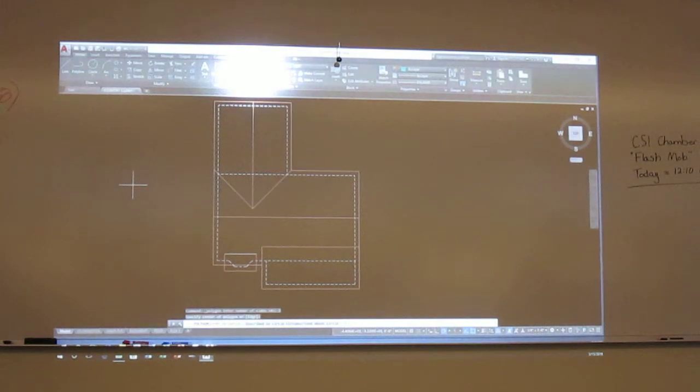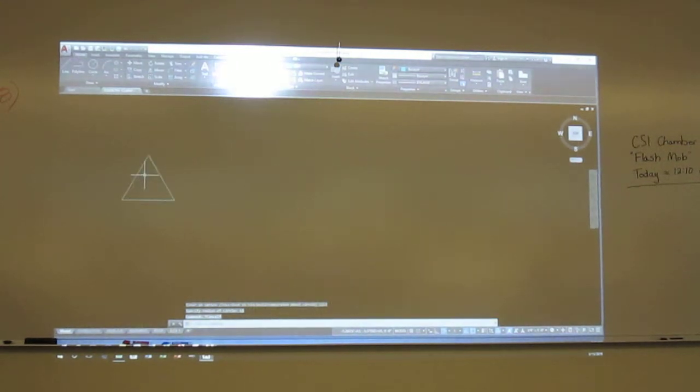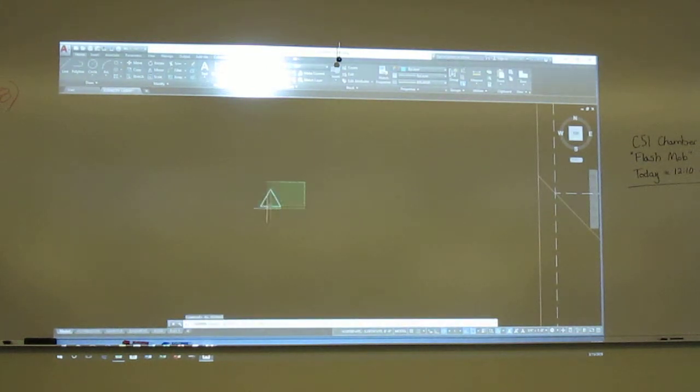And we're going to do an inscribe because I want the polygon inscribed inside, and we'll make that 12 units. So you're making this little triangle. Once you get one, just mirror it, and add a line in between the two, like such.